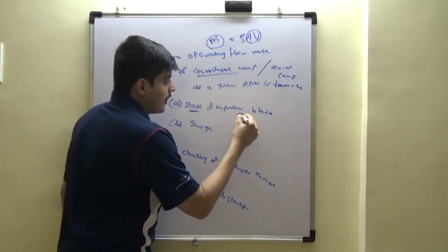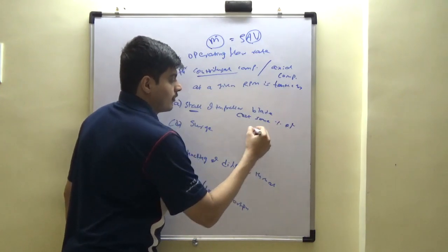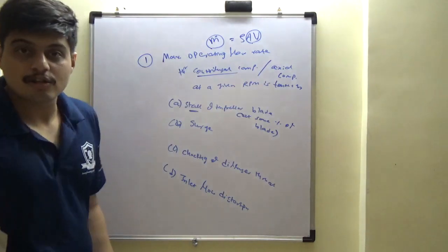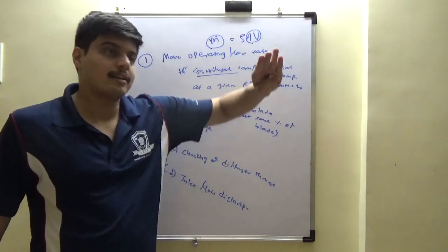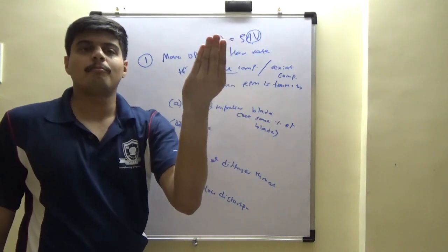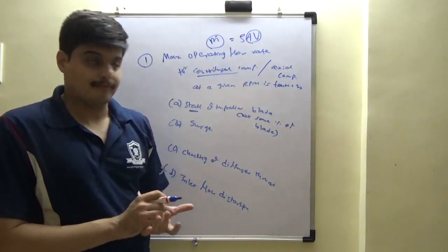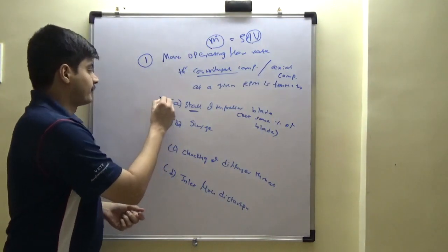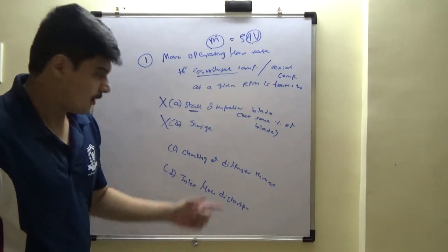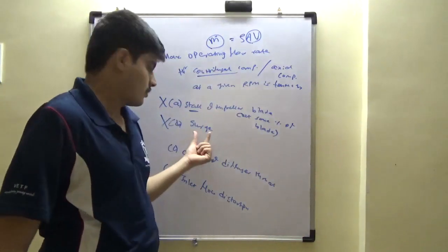Stall happens at some percentage of blade. Not entire blade can stall, right? We have seen these angles. It's twisted. Even if it is stalled at most of the sections, some sections will never stall. Obviously not. If you understand a centrifugal compressor surge, obviously not.